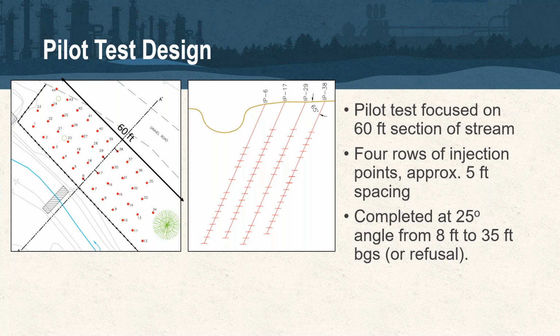Now, if you're going out with those technologies on the front end, you can certainly optimize that RDC process that I covered today. We know the plume is this size, we've defined that. Now we're going to go out and get our soil and groundwater data to use in combination with the high-res information, especially HPT. HPT is a critical tool, I think, whenever you're doing PRB designs, because it really helps you identify where those transmissive zones are. You can sample those, and it gives you really good mass flux measurements or calculations.